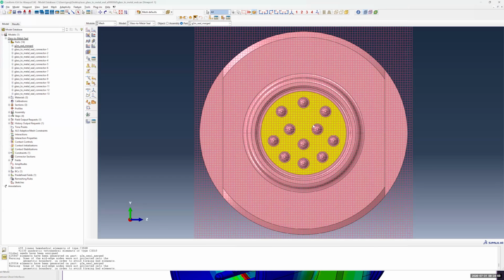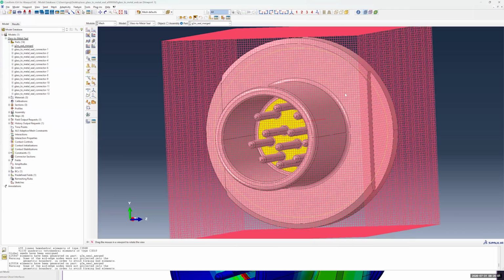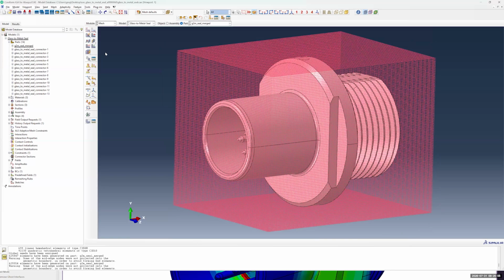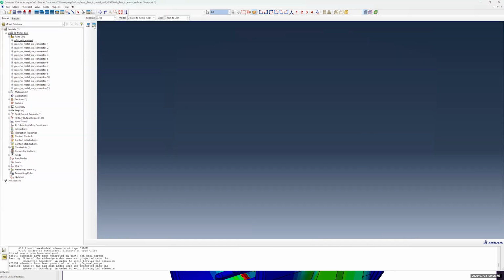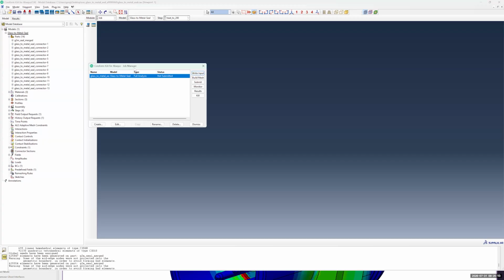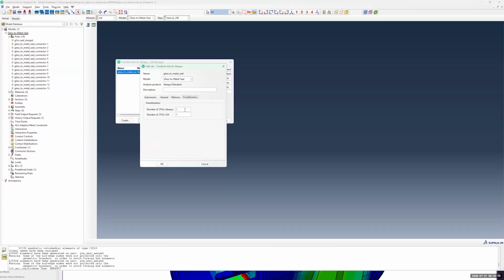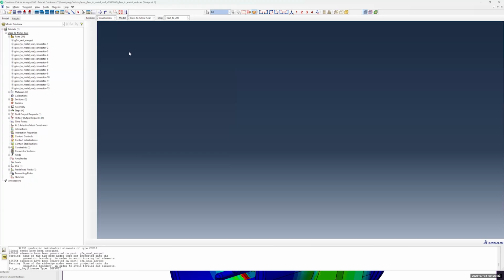And that's it. From a user perspective, I'm done building my mesh. I'm done meshing. The last step for me to do is just to create and submit my job. Here I've already created a job, so I'll just edit this. And I can essentially just choose to run, say, parallel for Abaqus and parallel for the volumetric trimming operation. I don't have time to run this analysis during this call, so I've pre-computed the results, which we can look at in the visualization module.